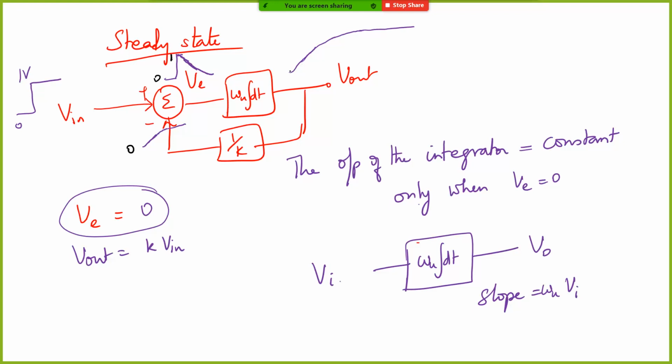And therefore now this integrator starts integrating, and once you start integrating, this voltage also starts increasing. Now as this is constant at 1 volt, and the feedback signal is increasing, what will happen to the error? The error starts decreasing, initially linearly. Then because the input Vi going into the integrator itself is reduced, let's say after a few nanoseconds it has come to 0.8.